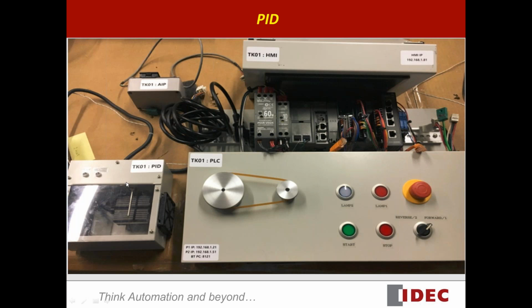Now, the heat gets trapped in that box, so to create a reasonable example, guys, I use the cooling fan. I'm going to control the cooling fan to create a load on that PID. Okay, so that's it. Really quick, my process variable is a K-type thermocouple into that PLC, and then my output is a data register.